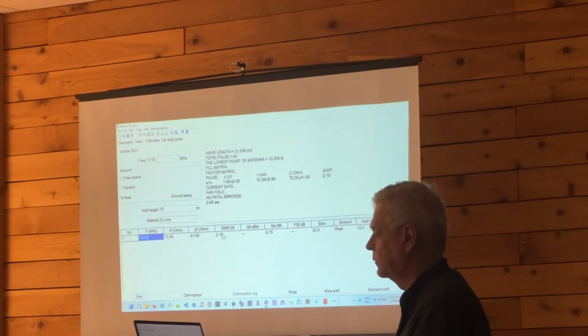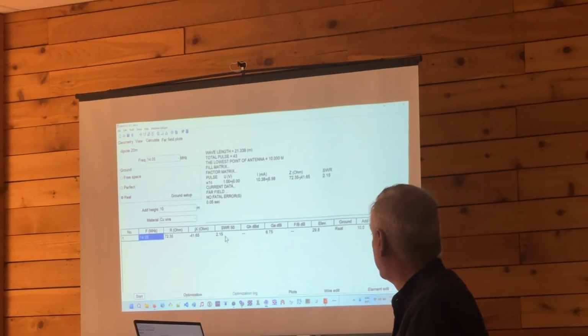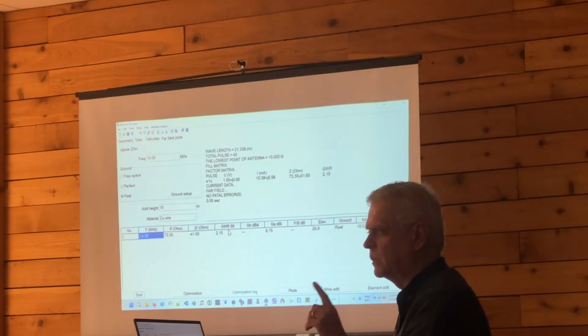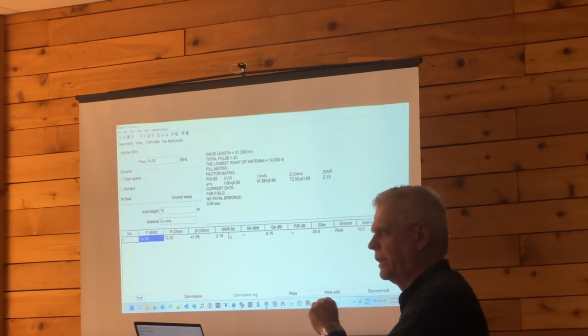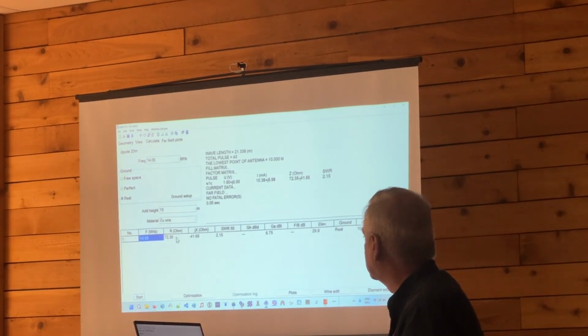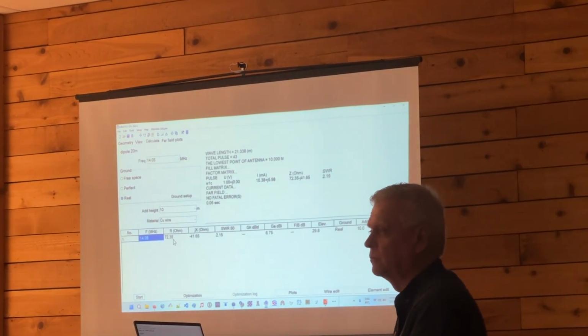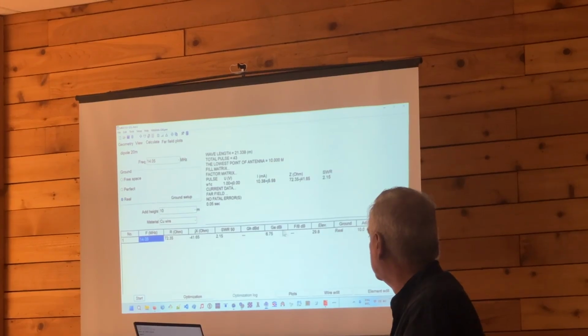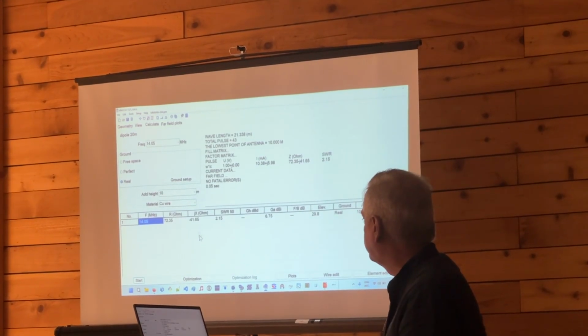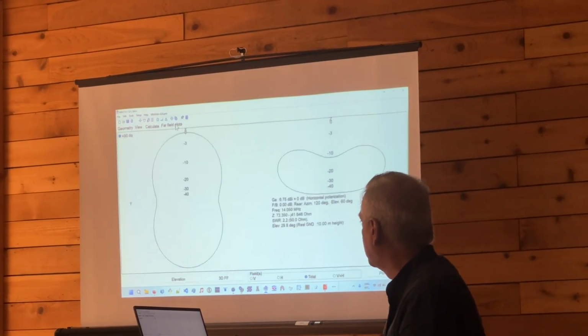Okay, just by that, we've actually come up with a 2.15 SWR 50. This 50 is going to become important in the final practical exercise we're going to do here. And then our input impedance, 72 ohms, not bad. Gain, very optimistic at 6.75. So fine, let's look now at our far-field plots.